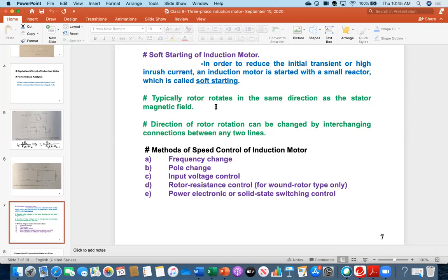For example, you notice that for an induction motor, the indicated or prescribed direction is clockwise, but you are noticing that it is rotating anti-clockwise. Then immediately you have to stop the motor and you have to interchange or swap any two lines. Then the direction will be fixed. So again, let me take you to that whiteboard, then it will be fine for you. These two green colored portions I'm talking about. So let me take you to the whiteboard once again.